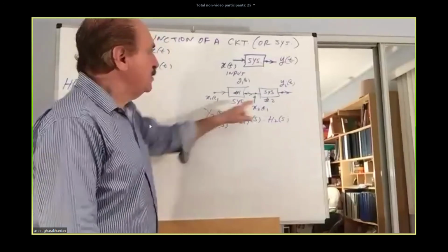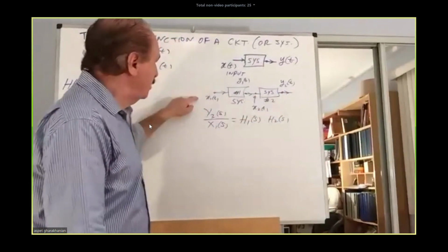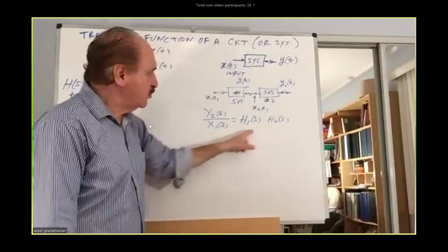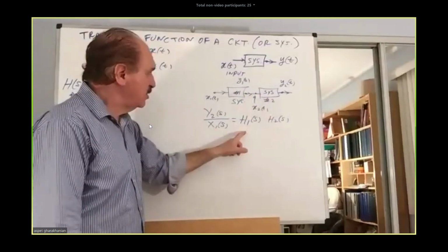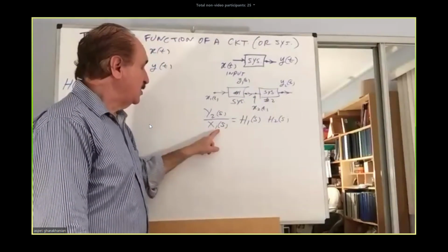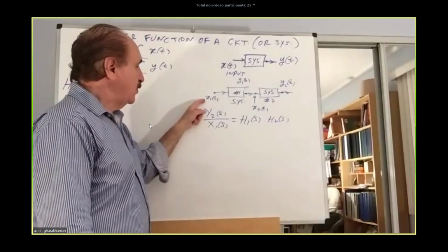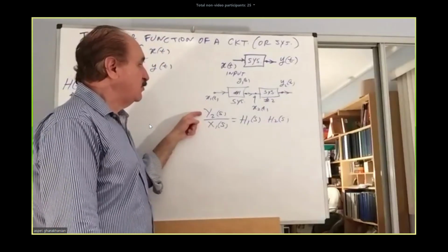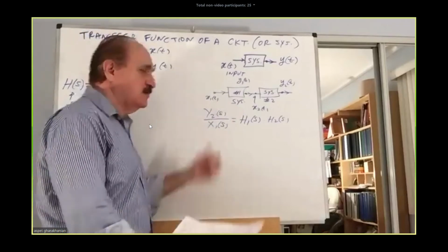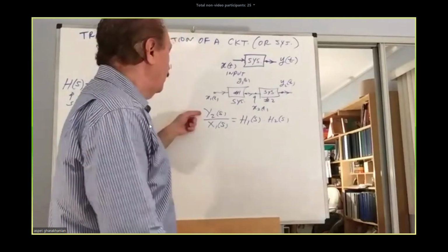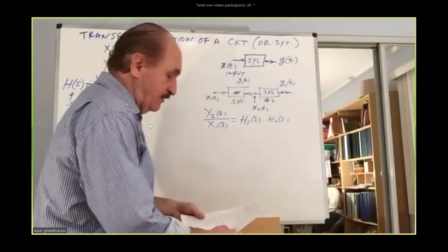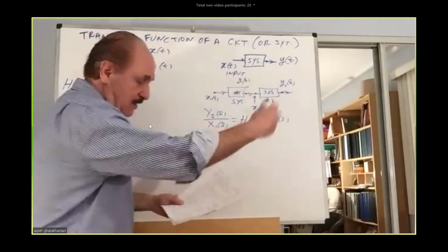Then, if you want to know what is the output in response to the input, you've got this product for each transfer function. You can get the Laplace of the input, multiply for the waveform that you're feeding in, and then you can calculate the output Laplace, inverse transform it, and then you can get the function of time. You will figure out what will be the time behavior.